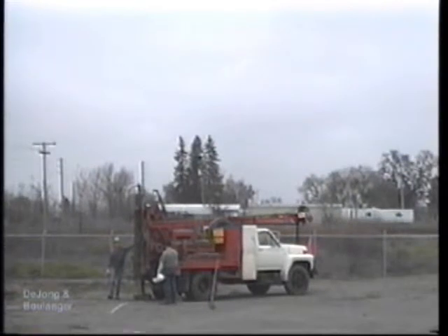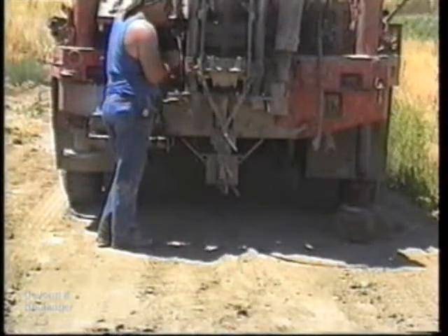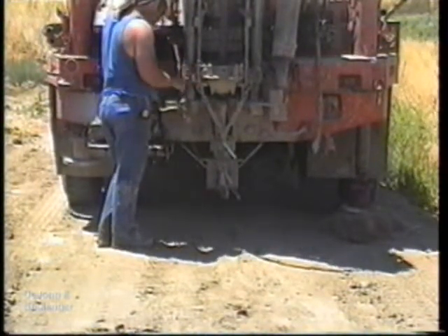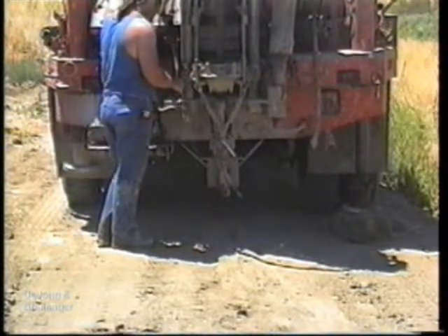This video presents an introduction to drilling and sampling procedures in geotechnical practice. A thorough knowledge of the tools and procedures is necessary for planning and executing, and a drill rig is leveled. If the rig is not level, the borehole will be angled, causing great problems in drilling and sampling, in addition to producing an inaccurate soil profile.